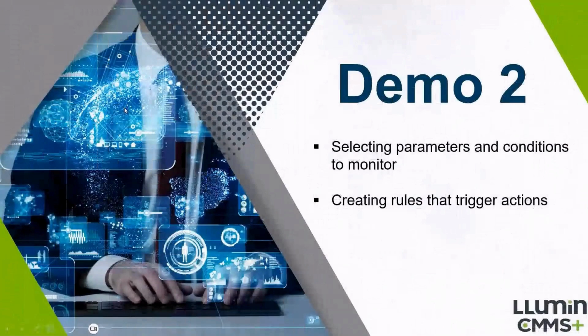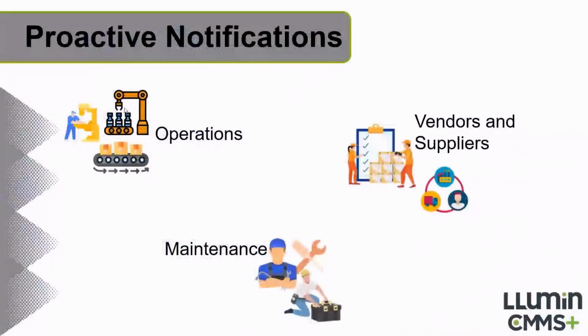All right, so now that we've set up some rules, we've made some decisions around what data we want to monitor, and then we've set up some rules around triggering off of that data, based on potential either usage levels or maybe conditions that have exceeded a threshold, or some analytics rules or whatever. So once the trigger event occurs, what we want to now do is set up the actions and notifications that need to be taken based on the type of machine that we're monitoring, and of course the data that has exhibited that there's a need for work or remediation.